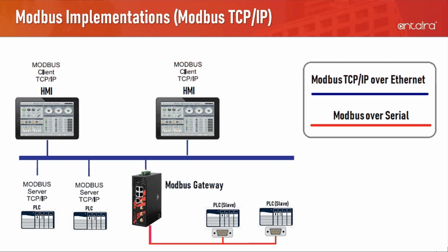First, both Modbus and Ethernet are supported by numerous manufacturers of industrial equipment. Second, there are no compatibility issues between Modbus TCP/IP and the already installed Ethernet infrastructure. Lastly, Ethernet communication offers faster data transfer rate than serial communication.